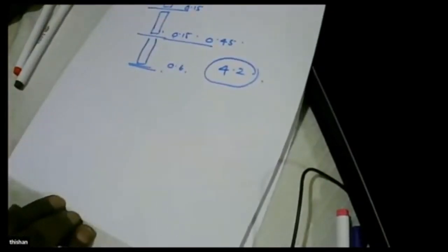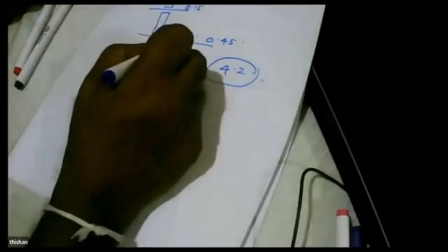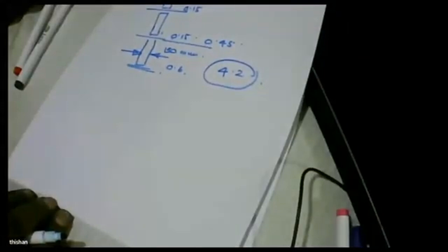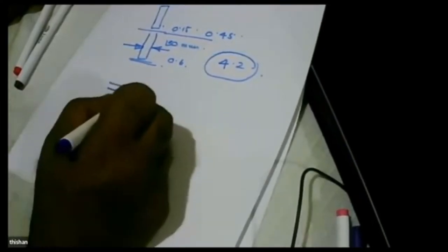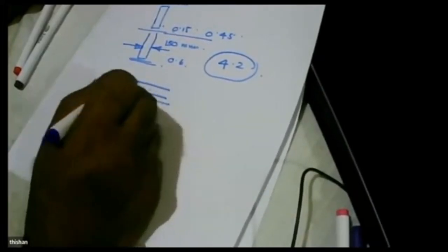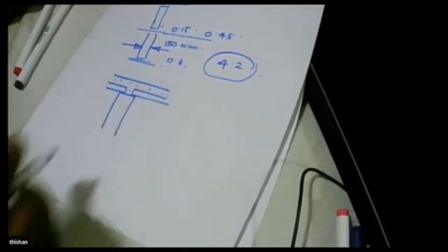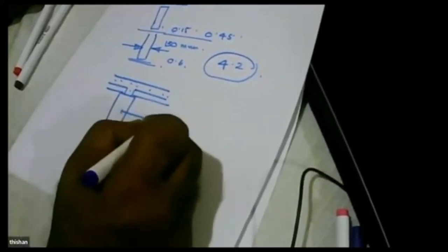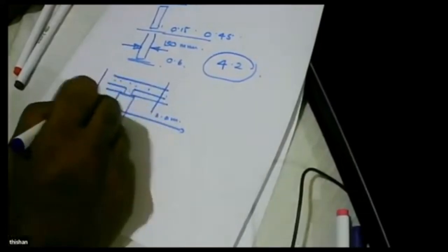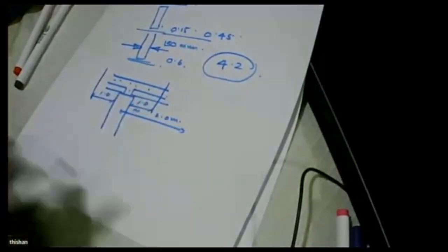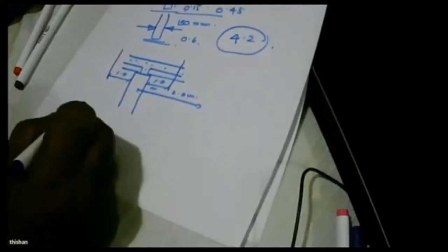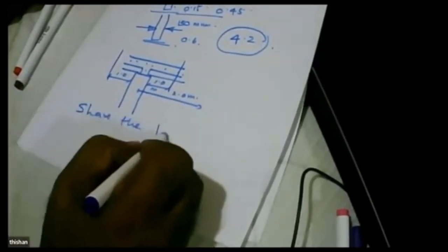So you can see there's a good possibility to complete the walls with a wall thickness of 150 millimeters and still have a factor of safety of over 4.2, provided we place the concrete slabs on the wall directly and make it continuous so that each slab will span 2 meters, providing a load of 1.0 meter width onto this. So the whole idea is: share the loads.